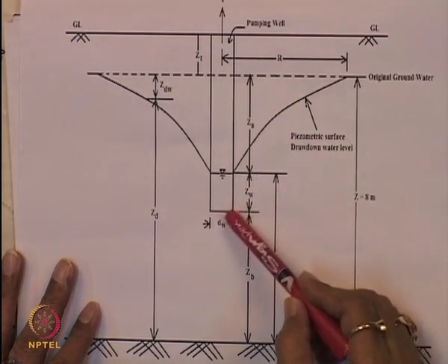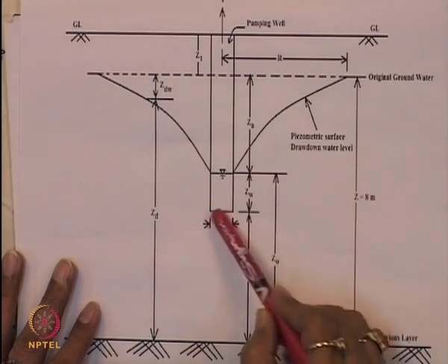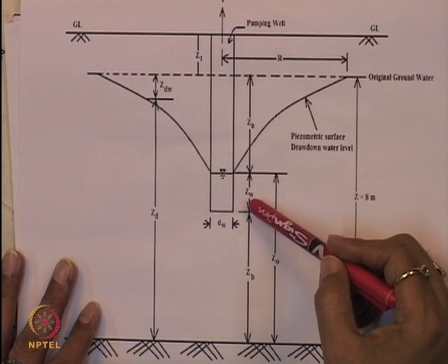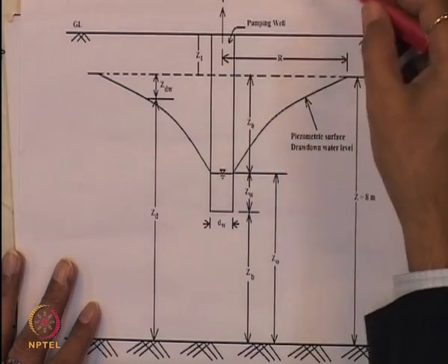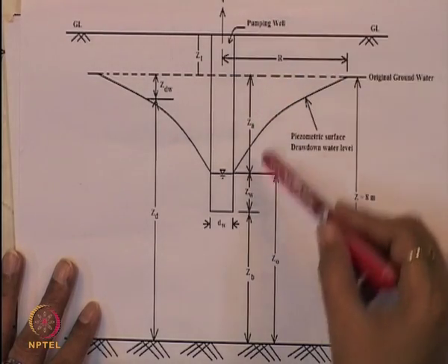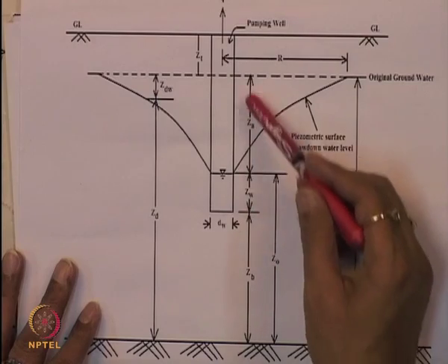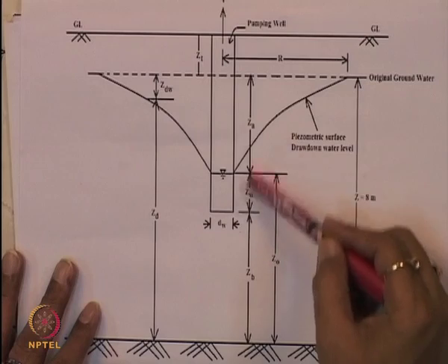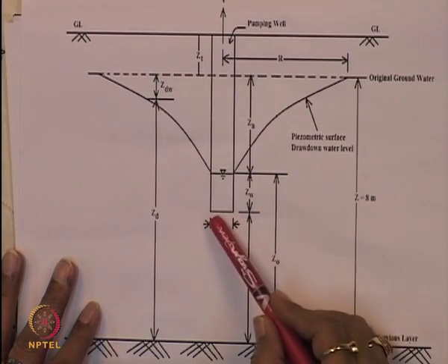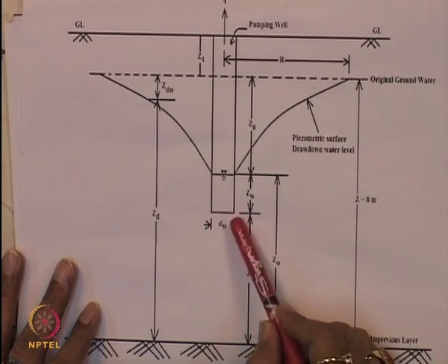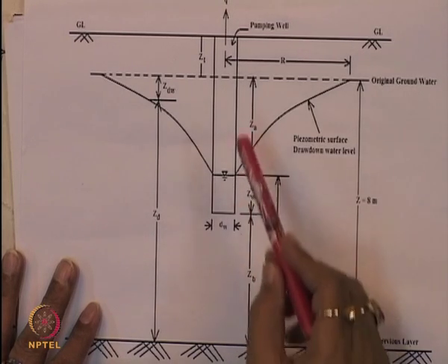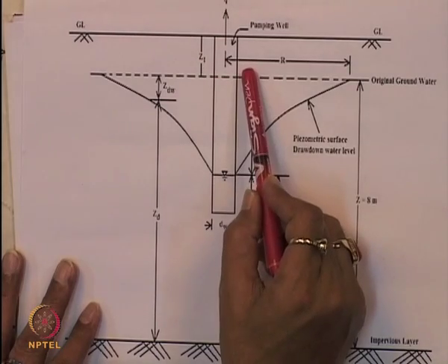So we have to provide the geotextile material into this drainage, whose length will be ZA plus ZW, and this length is Y. So Y into 2 times (ZA plus ZW), because this side and also this side, plus 3 dW, because we are giving the bottom one and the top one and then the overlap one.